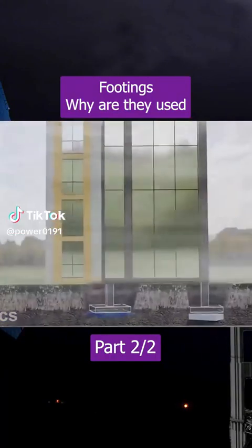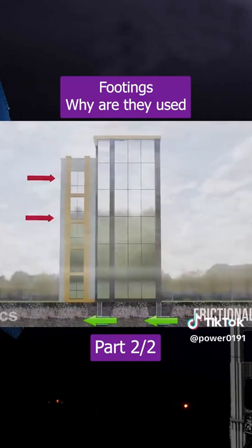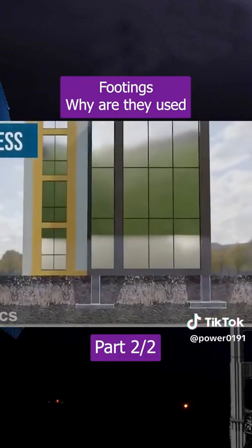Additionally, if this structure is subjected to lateral forces like winds, floods, etc., footings will help your building avoid sliding as a result of frictional resistance between the footing and the soil. Now the second design aspect, the thickness of the footing.